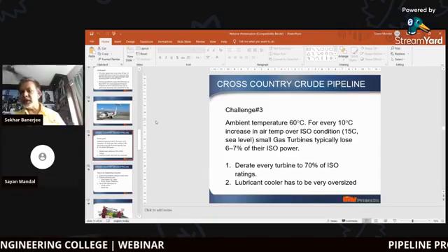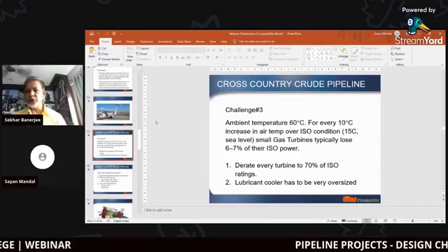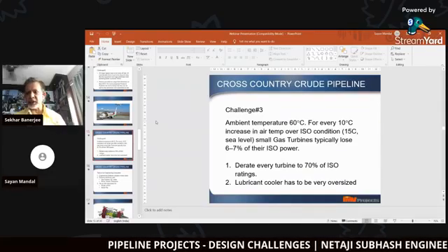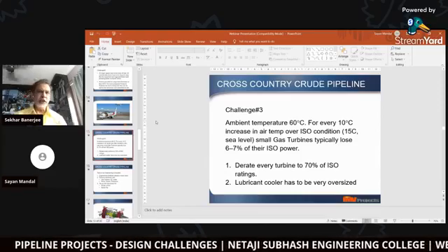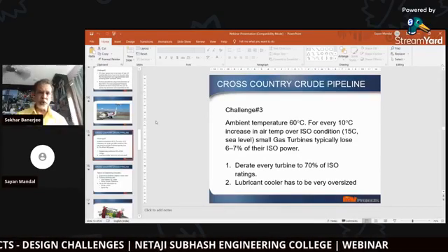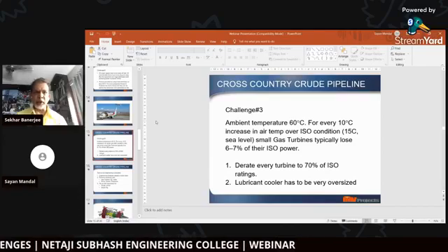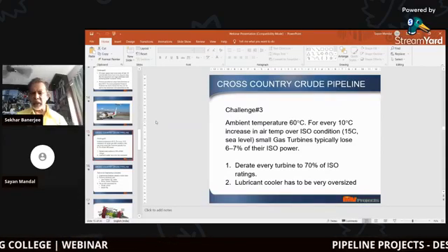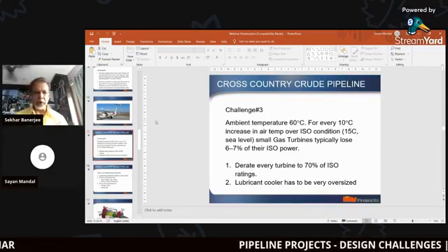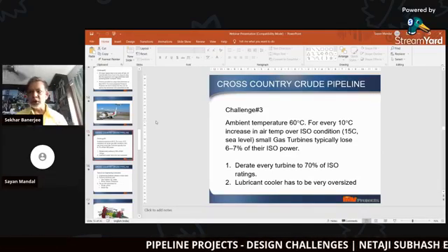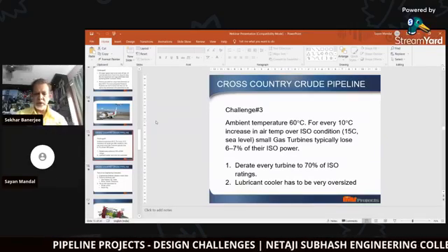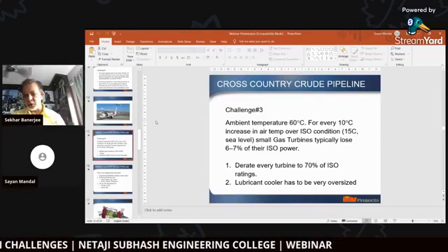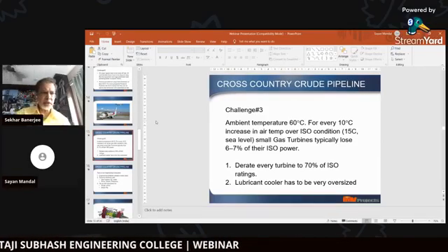Now at 60 degrees centigrade air temperature, we have to reduce the hot oil to that temperature, 60 degrees, and then it will go up to the bearing and go to 90 degrees and come back, and it has to be brought down to 60 degrees immediately. So we have to have a very large lube oil cooler. Basically, double-sized lube oil coolers are installed. So we calculated the whole project based on these sizes of equipment. Next slide, please.